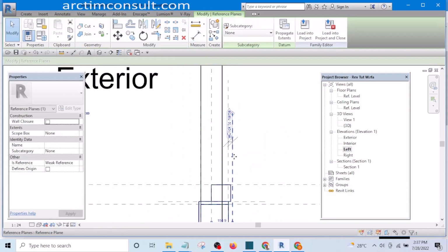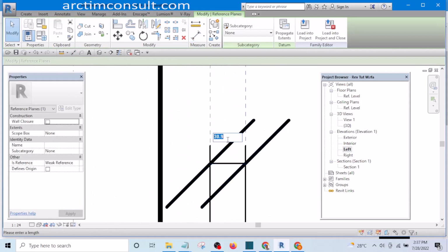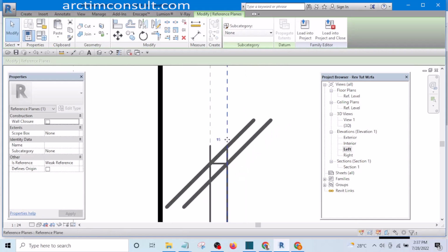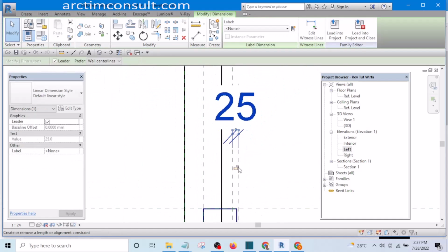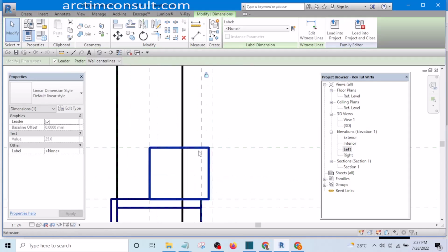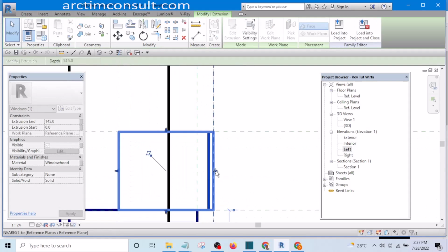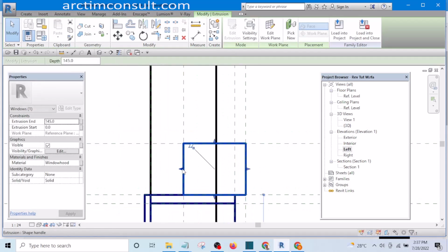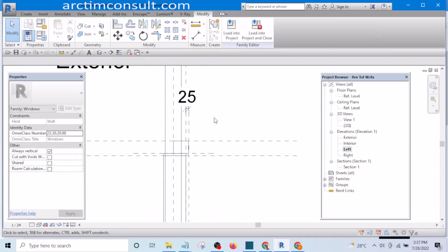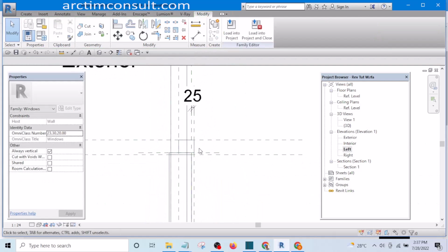And if this is about 1 inch, that is 25 mm. 25. And press enter. Then constrain it and stretch this one to here and constrain it. Then you can also stretch this to here and constrain it, so that it will be intact at any point in time.